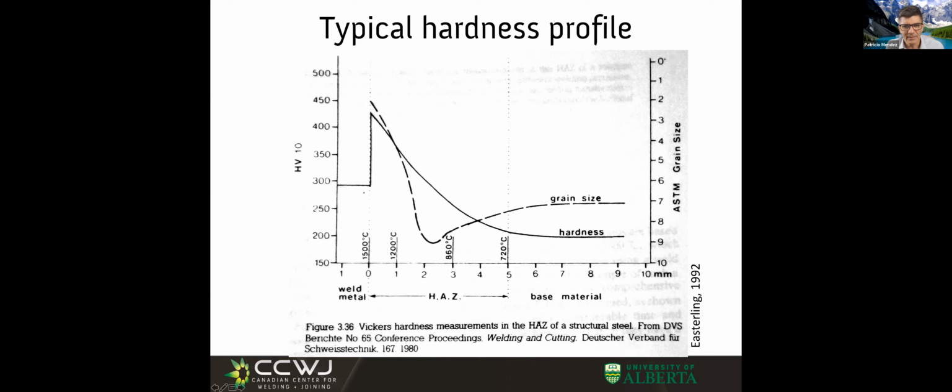look at this, it's kind of an ambivalent graph. It's kind of an ambiguous graph. It shows something you do measure, hardness. There is some hardness in the base metal. And as you go through the intercritical region, hardness increases, and you go through a fine grain heat affected zone, hardness increases, and by the time you get to the coarse grain heat affected zone, you have a very high hardness.